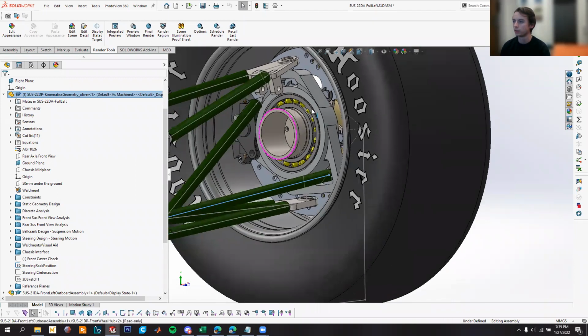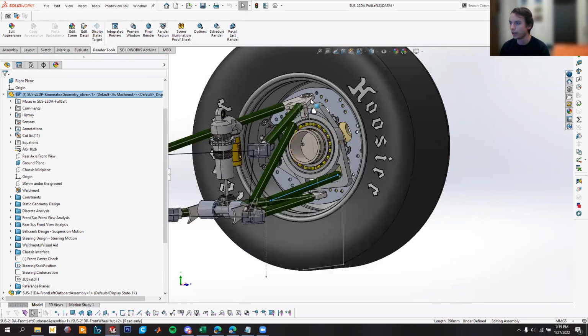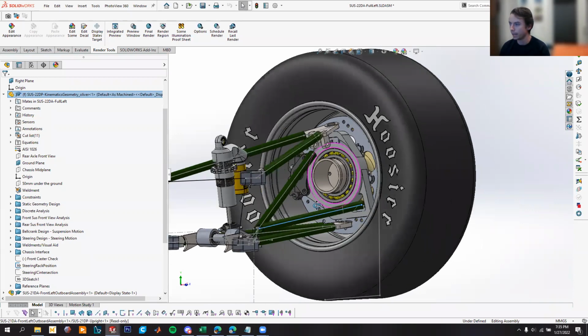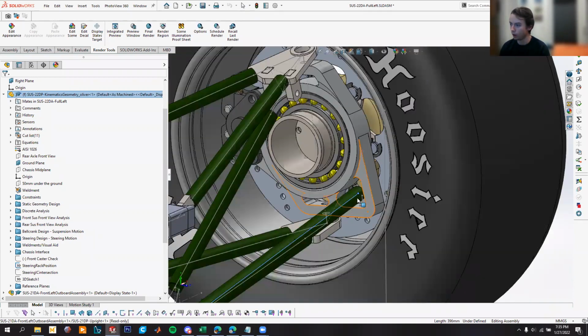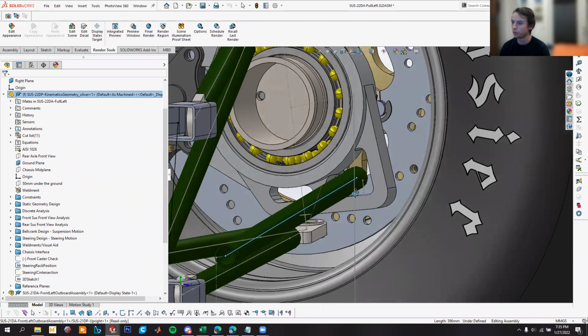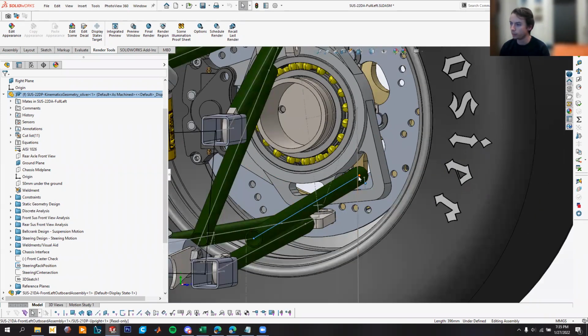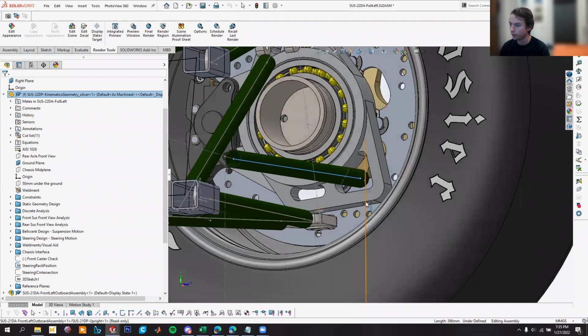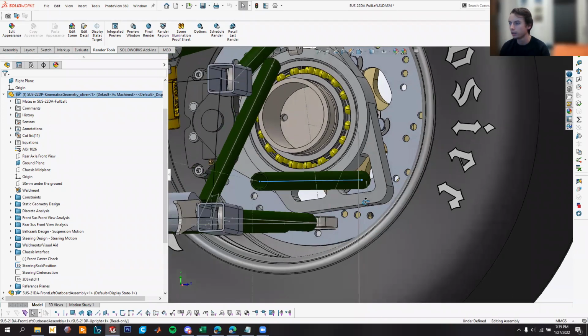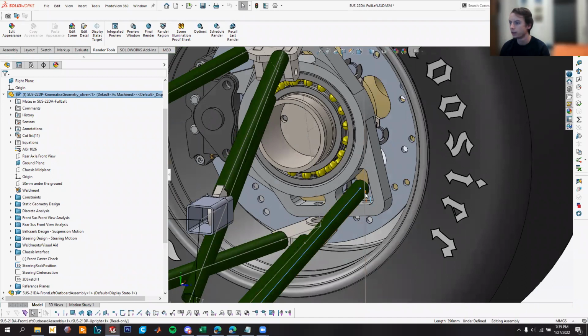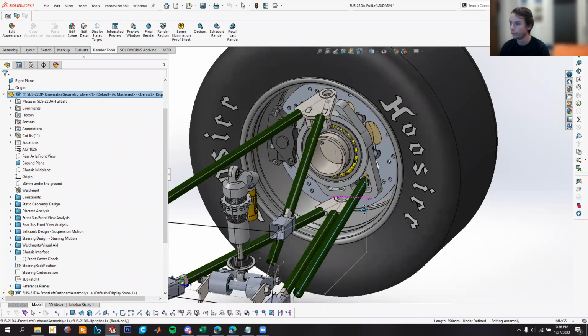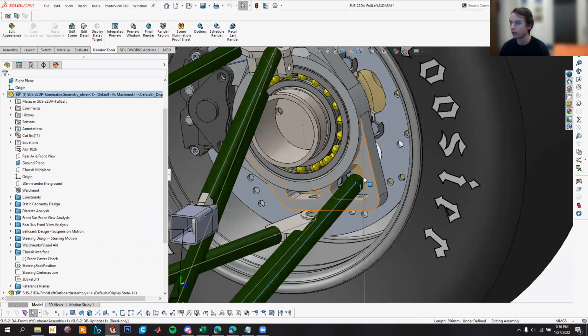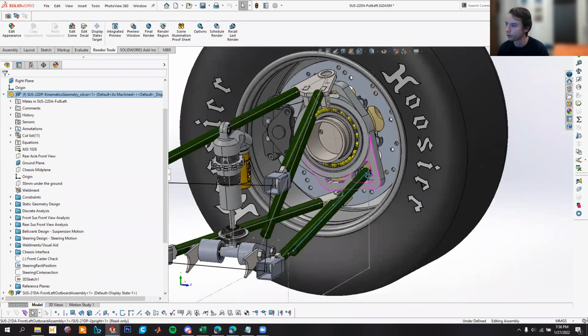So this outboard suspension is all the same as last year, and we are going to reuse it. One modification we did do was we moved the outboard steering link position from beneath the upright to inside of this pocket to allow more clearance with the wheel shell here. And so hopefully that will work. It may require some modification of the upright, but nothing that will compromise its structural integrity.